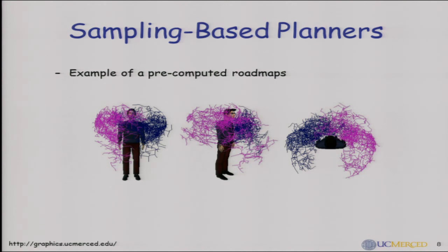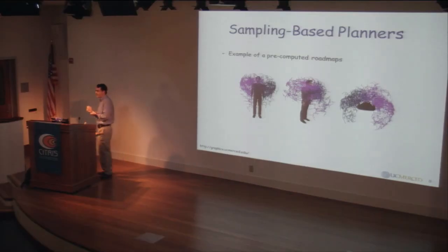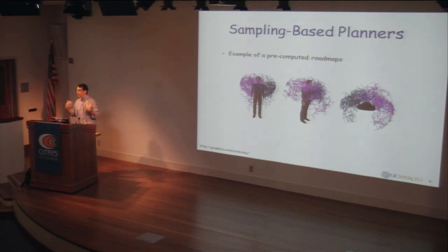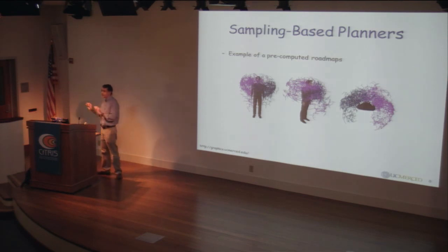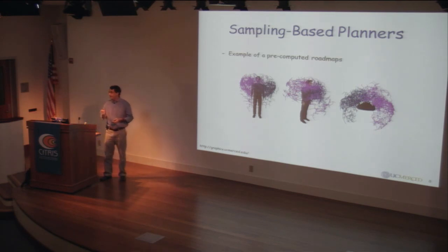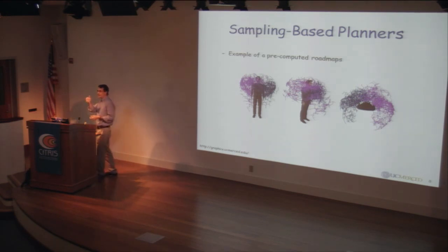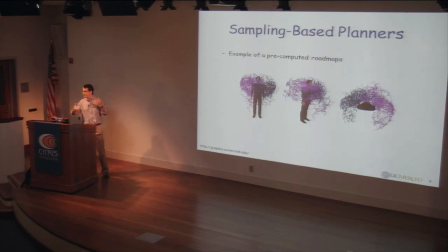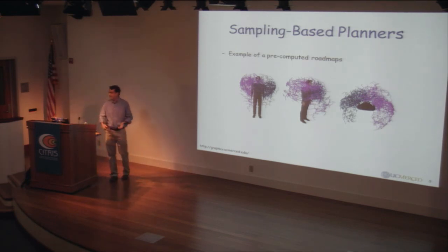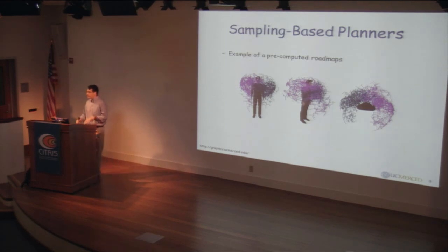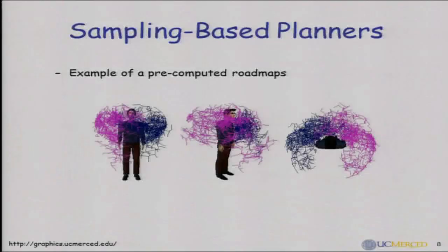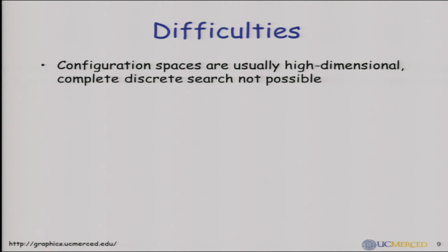Here in this graph, every node represents where the hand can reach, but each node is associated with a full body configuration. And actually, we simplify the full body configuration by a 22 degrees of freedom control layer. For instance, you saw in the example that knee flexion is controlled only with one vertical translation degree of freedom. And then with inverse kinematics, we figure out what the joint angles of the legs are to achieve that amount of knee flexion. So with that control layer simplifying the problem, we have a representation of the reachable volume for this character, and we can search it for solving problems, right?